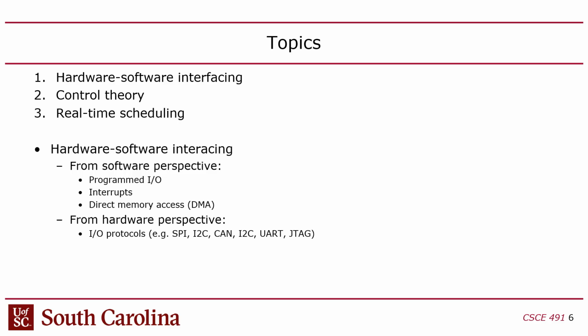And then finally, real-time scheduling, a real-time system. Another aspect here is that whenever you design a control system, its processing has to keep pace with the physical world. So there's this notion of a time step. You have a time step which determines the cadence of reading the process variables and updating the manipulated variables. Your processor has to be fast enough. It has to be guaranteed to be fast enough to achieve a certain level of performance